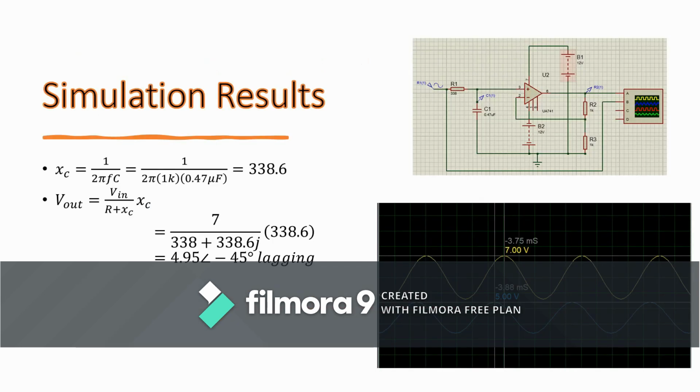So this is the simulation result I built on Proteus. For the value of R and C, I can obtain them by using the formula stated just now, which is Fc equals 1 over 2 pi RC. I will fix the value of the capacitor because in practice the cutoff frequency will not be as accurate as the value we need, so we need either a variable capacitor or a variable resistor in order to change the value to get the cutoff frequency we need.